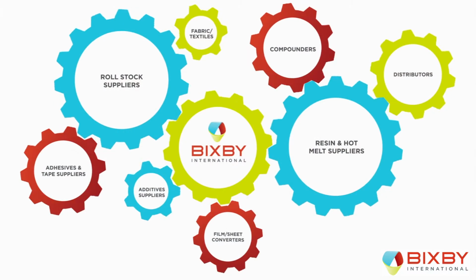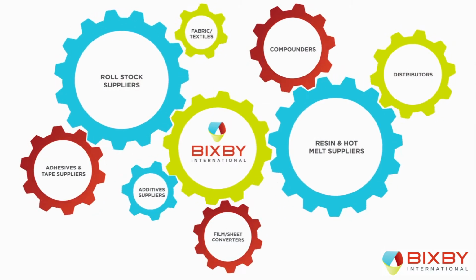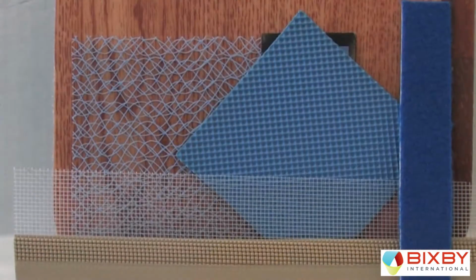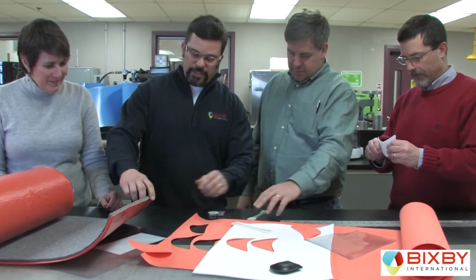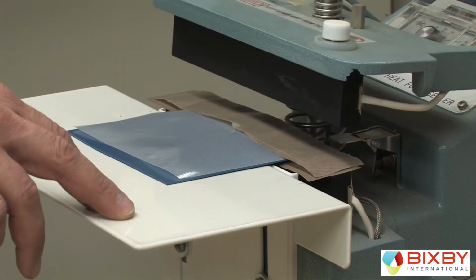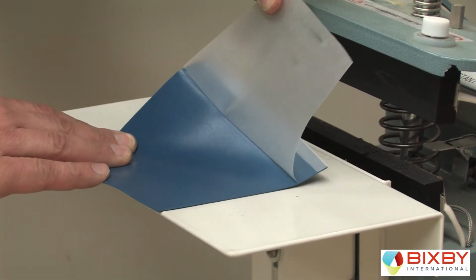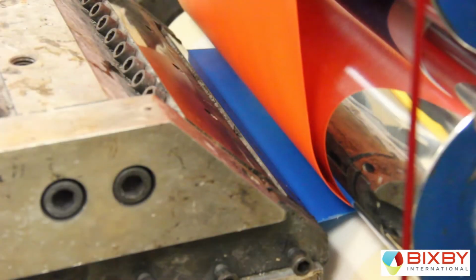Extrusion lamination is at the heart of Bixby's process. The company's success stems from the fact that it has relationships with many dozens of material suppliers and their technical experts. This enables Bixby to choose and formulate, if necessary, the core thermoplastics, hot melt polymers, additives, and superstrate and substrate materials to assure compatibility with a laminate system. Moreover, Bixby's process enables it to gain a thermal melt bond in process, often without the need for additional adhesive chemistries. This is achieved by extruding molten polymers between functional layers, whether that's foam or reinforcement or our extruded web.